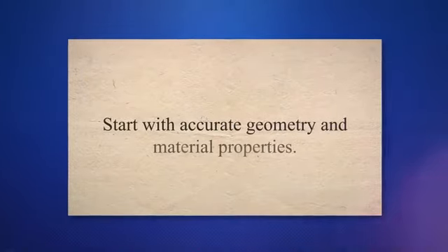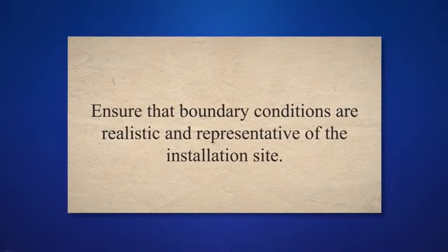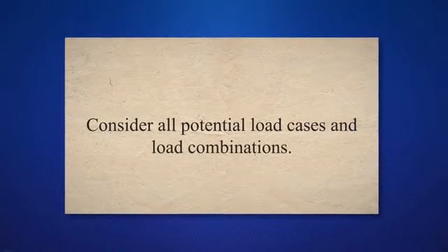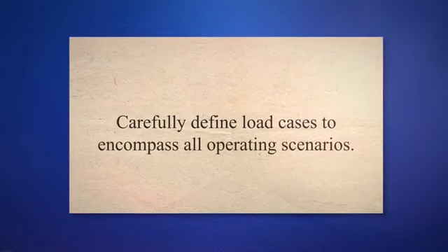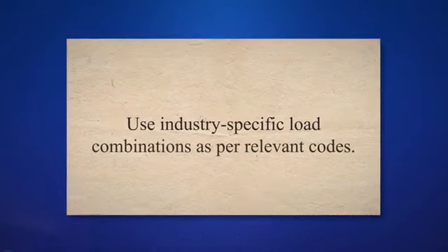Start with accurate geometry and material properties. Ensure that boundary conditions are realistic and representative of the installation site. Consider all potential load cases and load combinations. Carefully define load cases to encompass all operating scenarios. Combine load cases to assess the most critical conditions. Use industry-specific load combinations as per relevant codes.